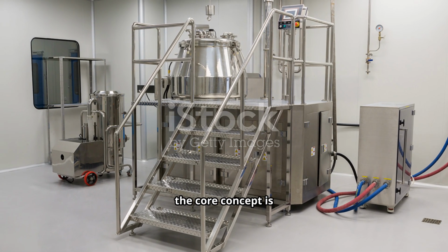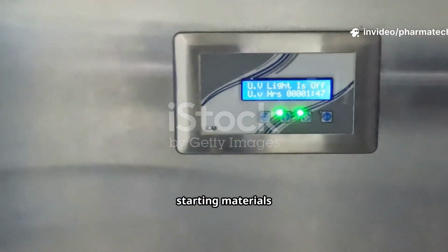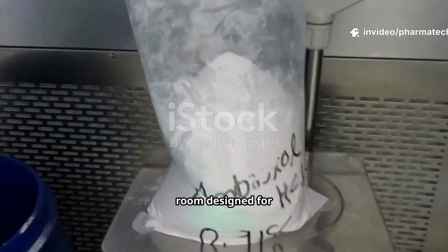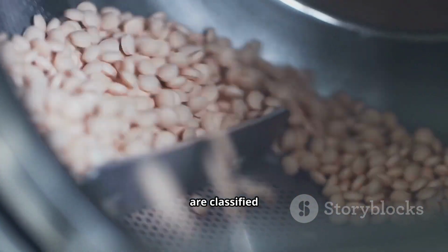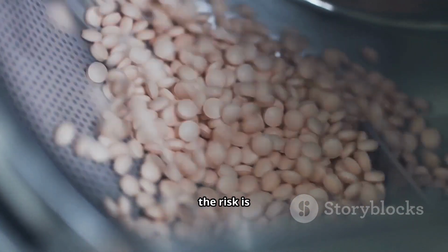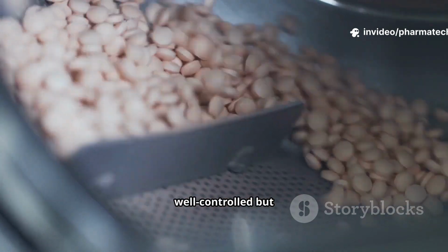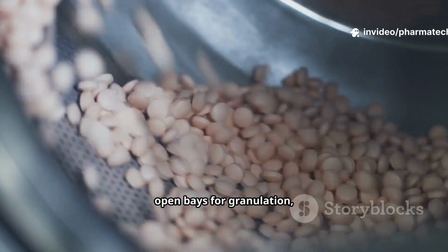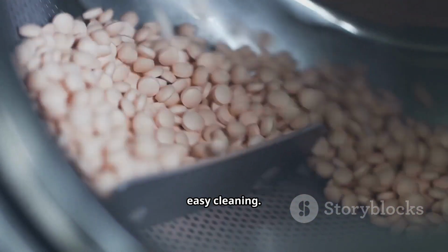The core concept is zoning based on product and process criticality. Weighing of starting materials usually should be carried out in a separate weighing room designed for such use. For oral solid dosage forms like tablets, the areas are classified environments, like ISO 8, grade D. The risk is contamination from other products or microbes. These areas are well controlled but don't require the highest level of sterility. You'll see large open bays for granulation, compression, and coating, all designed for easy cleaning.